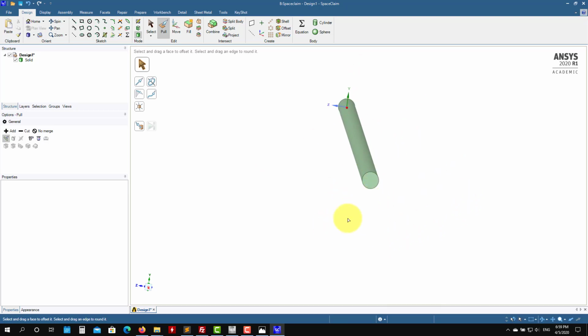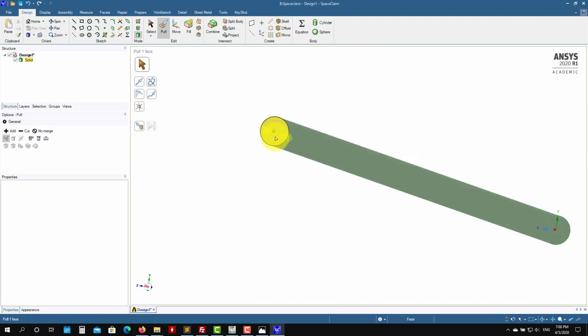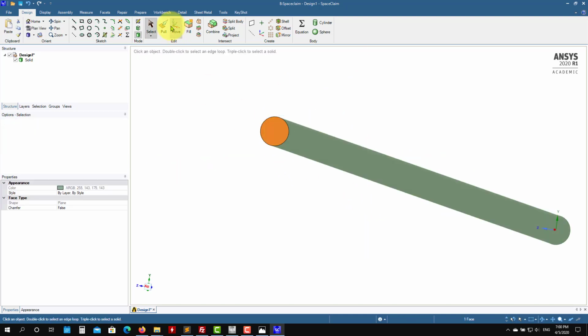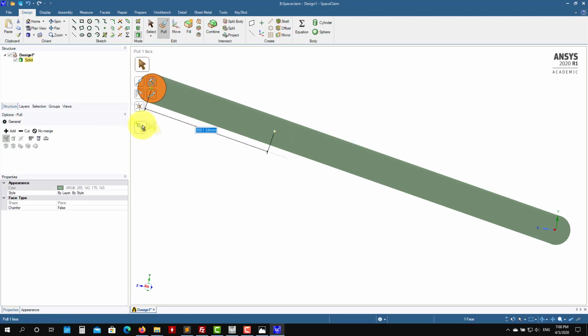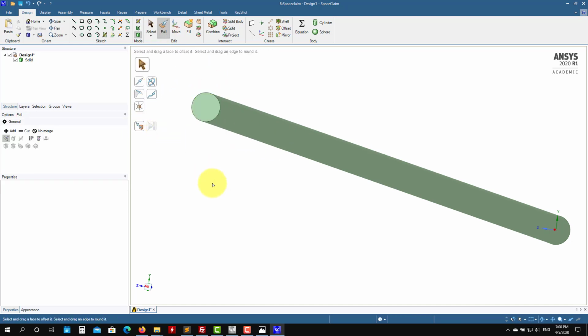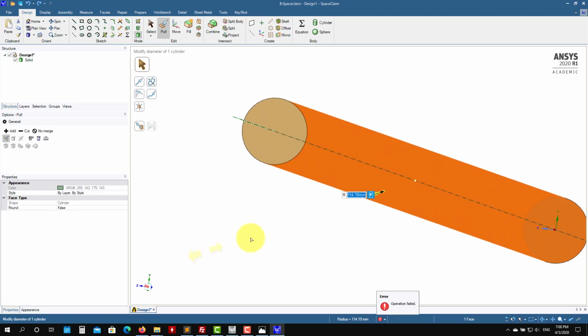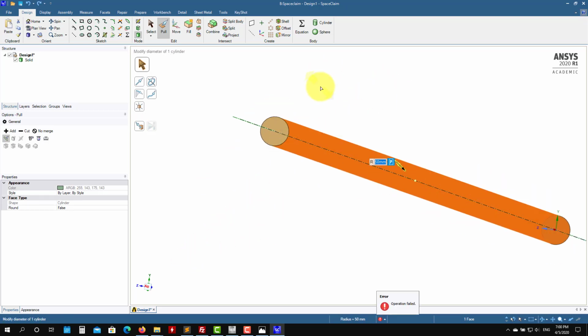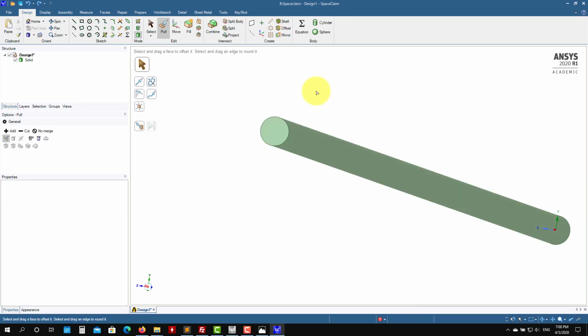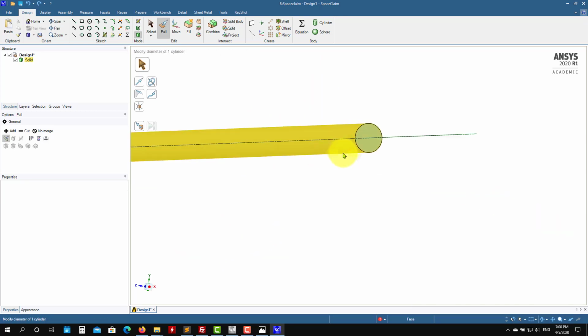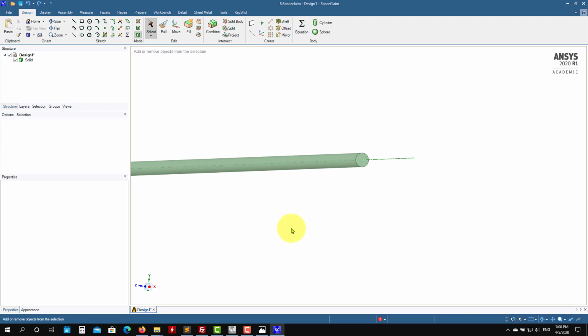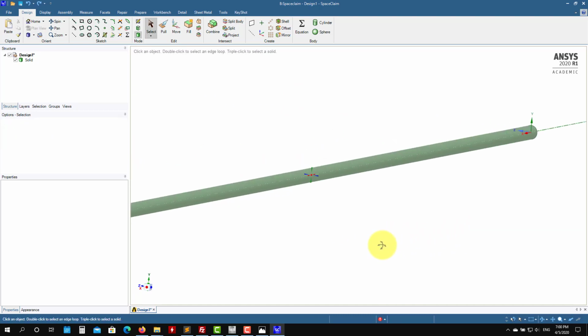Okay. And then you can create new geometries, do the intersection. So for instance, now I want to extrude this face here. So you select here, pull, and then you can do a new extrusion. Okay, and the same with the diameter. You can pull there and you can change the diameter. So this is kind of like working with clay, pull in, pull out, rotate. Very powerful.